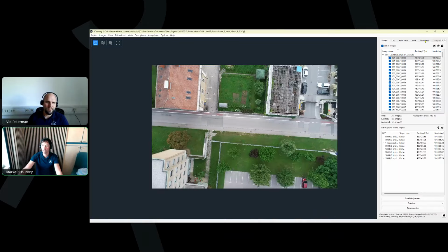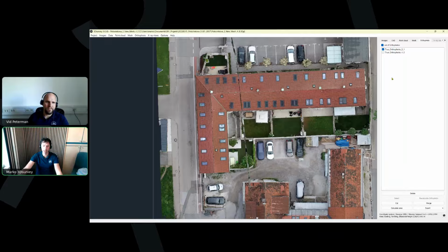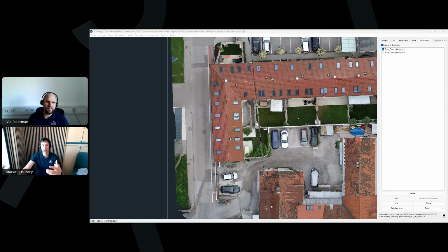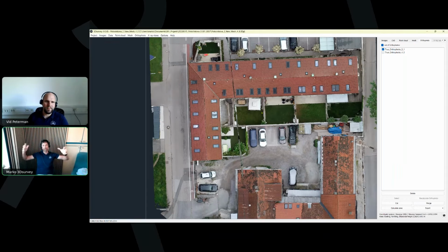First one, I would continue in the same example. The true orthophoto is actually the top-down render from our full 3D mesh. And if the 3D mesh is improved, the true orthophoto is improved. The true orthophoto is really important if you are in an area where you have a lot of buildings, big holes and everything like that. You can't get nice results with traditional orthophoto there. The true orthophoto is a must have, and if you have some side images, this is the perfect tool.